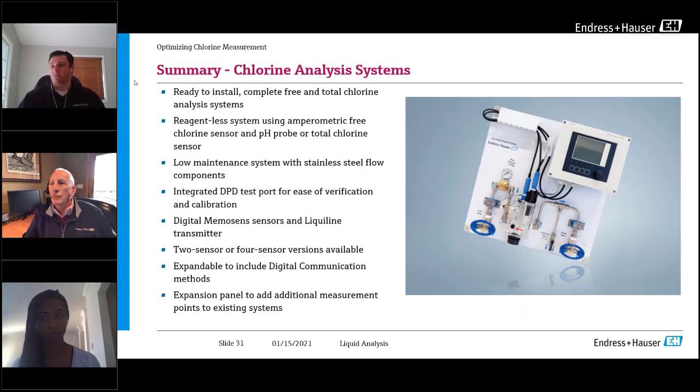Yeah, I would always recommend having a filter in there. It's kind of hard to tell without being able to really see the flow block, but the way it's designed, the flow block actually has a channel where it points the flow directly at the head of the sensor. So it's a pretty small channel in there. So there would be no issue with putting the filter in there. I guess maybe the only issue is if the filter slows down the flow too much, but I don't think I've ever seen that be an issue.